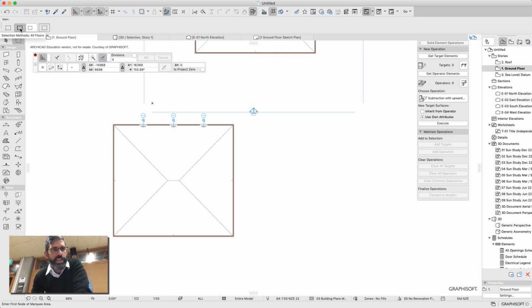Oh yeah, here we go. So if you select it, somewhere around here is a polygonal marquee or a marquee on an angle. Okay, so you might go, I need all of these windows in here, so draw this crazy little marquee, go to the window tool, go Control A, and it'll select all of the windows in that marquee, rather than go select. Oh, I just deselected.